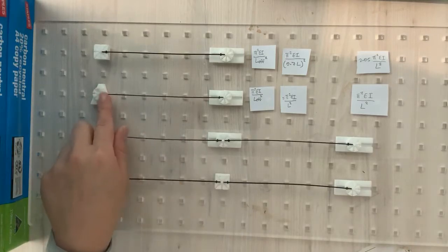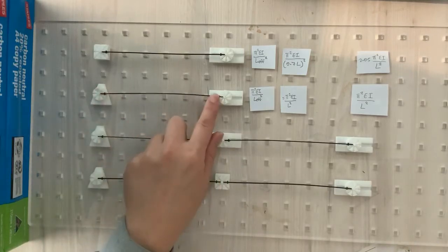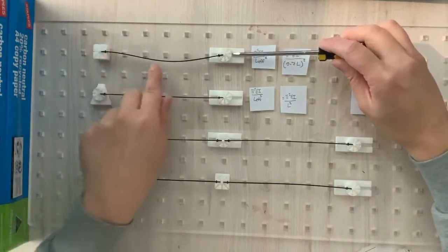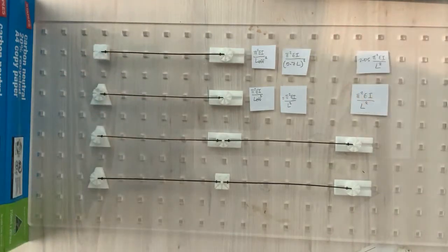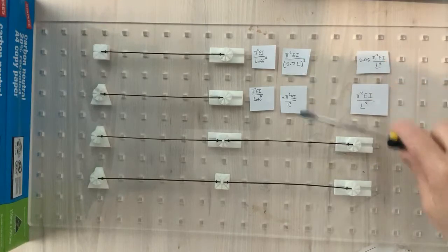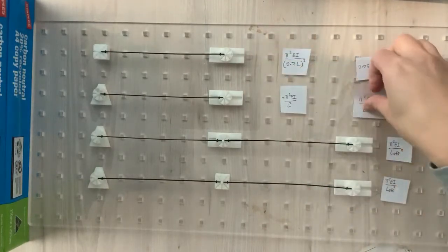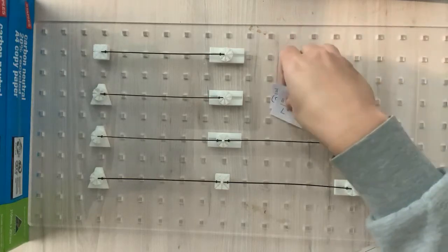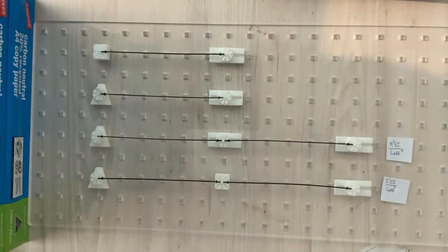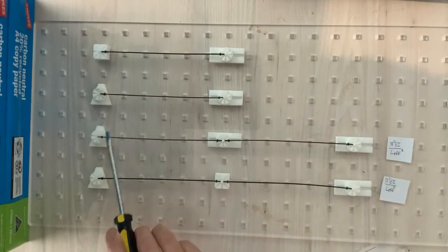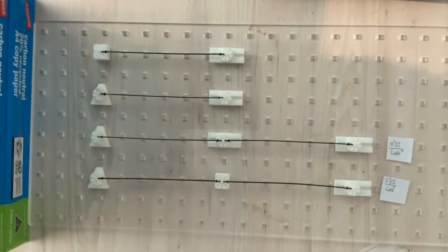In this one here, you would use an effective length of 1 meter, and in this one here, you would use an effective length of 0.7. So in that way, we can relate everything back to the effective length calculation, pi squared EI over L squared. And once you know what the effective length is, you just drop it into these equations here. So in this case, the effective length is 2. In this case here, the effective length is 1.